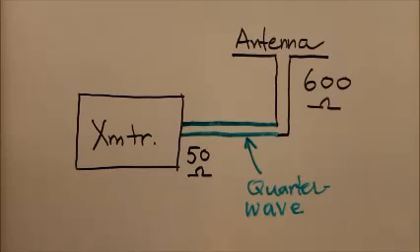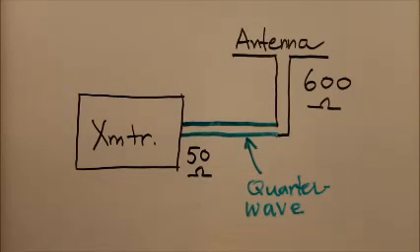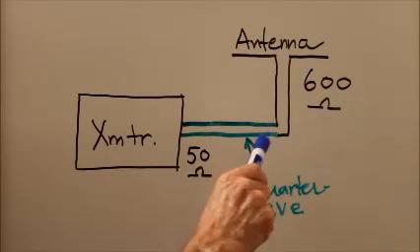Well, now the quarter wavelength matching section will represent an electrical quarter wavelength, which will be somewhat shorter than a free space quarter wavelength, depending on the type of transmission line, and that involves figuring out the exact length of that. We'd need to know the frequency, and we'd need to know the so-called velocity factor of the line, where the velocity factor is the proportion of the speed of light that the electromagnetic signal actually follows. But that isn't really relevant here.